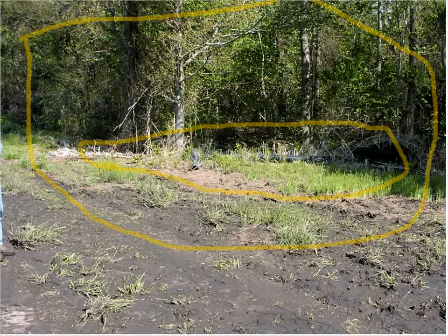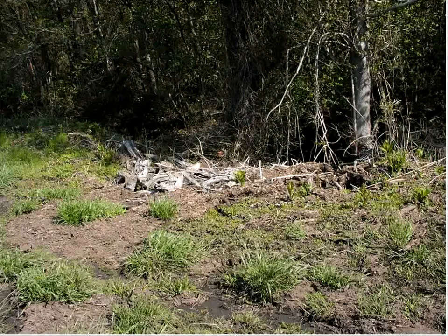You can see from the soil that's piling up here that you have concentrated flow. You can see from the junk that's piling up here that you have concentrated flow. You cannot count this buffer because it is a non-effective buffer. So just because you have a buffer there doesn't mean you automatically get credit. You must look at your buffer to make sure you're getting sheet flow.